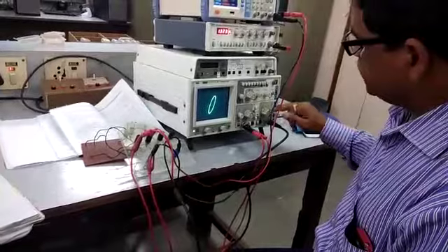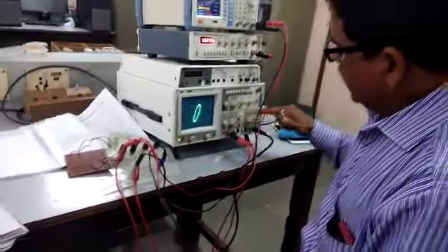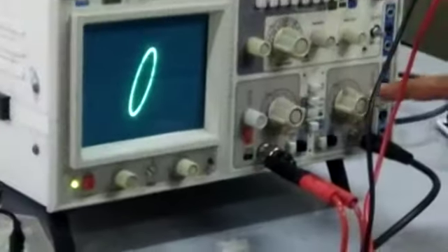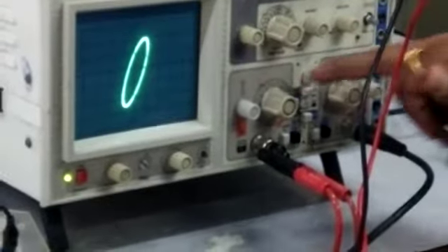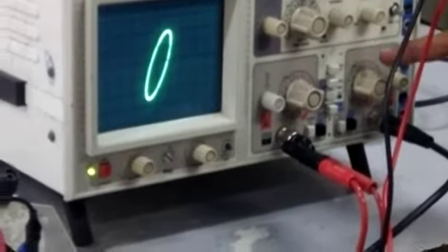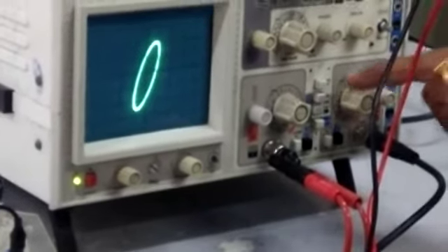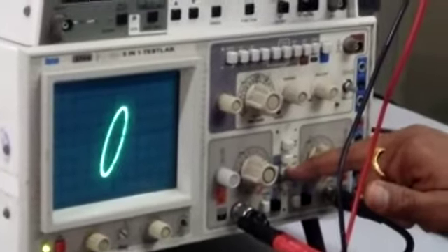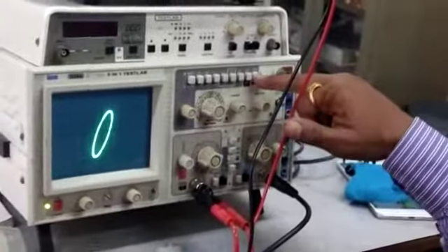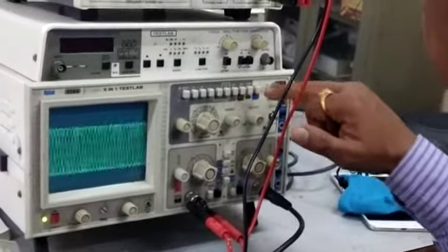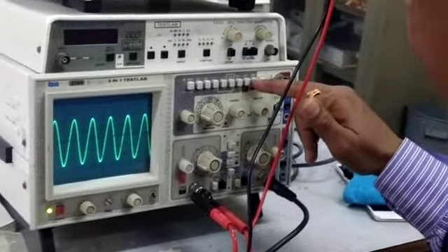Now one more thing here, and it is a very important thing: for channel A and channel B, channel 1 and channel 2, these two volt division knobs should be kept at the same value. This is the important thing. Then next, push XY mode. But you know, in the previous practical we have seen how Lissajous pattern is obtained. Lissajous pattern is obtained only when XY mode is pressed. Now my XY mode is pressed here. If it is removed, then only the sine wave will be there, and of course the phase shift.